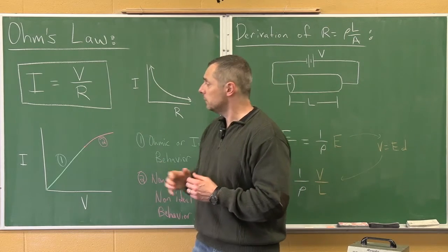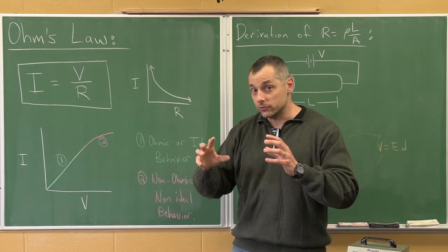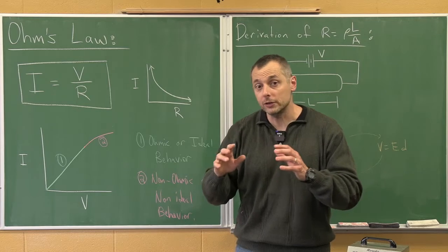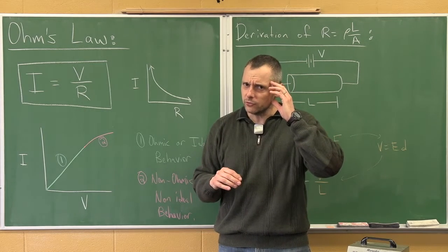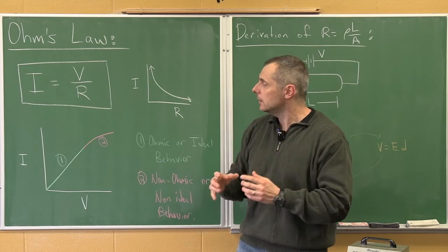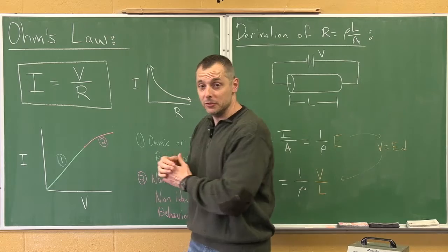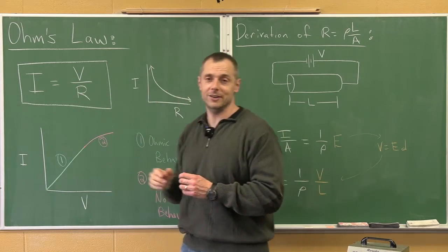And the same thing for resistance. If I were to say, okay, I've got an electrical circuit and somehow I make more resistance in it, does that make more or less current in the circuit? Most people would probably say, more resistance, probably less current. And you would be correct. So this equation is very much common sense. It's very nice. More volts, more current, more resistance, less current.